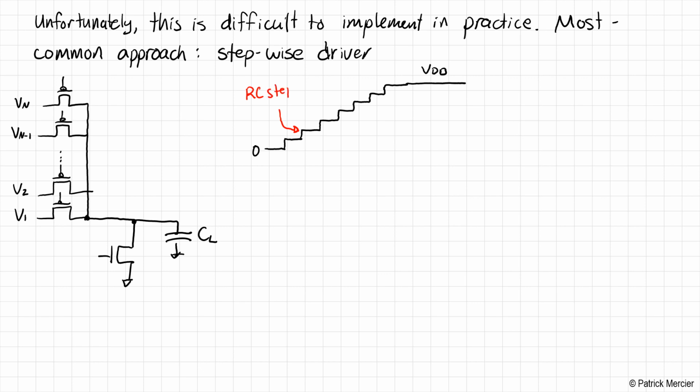So there is an RC time constant associated with each one of these steps. Okay, but if we make the RC time constant small, you can go through the math and you can see it's actually C delta V squared that's occurring here. That's the energy loss here. And because it's delta V squared and delta V is smaller than VDD, the net result of energy dissipated in the circuit is actually quite a bit less.